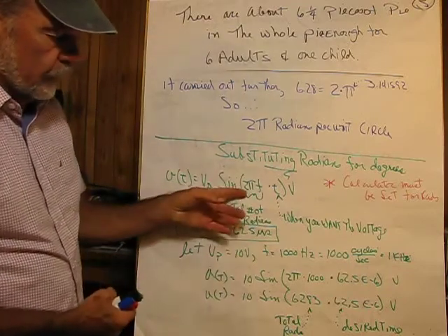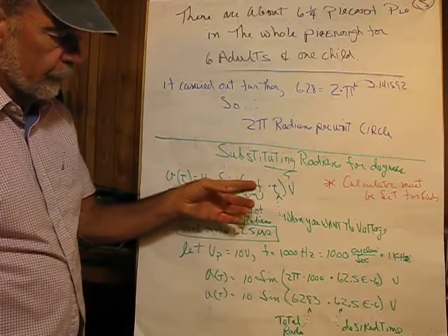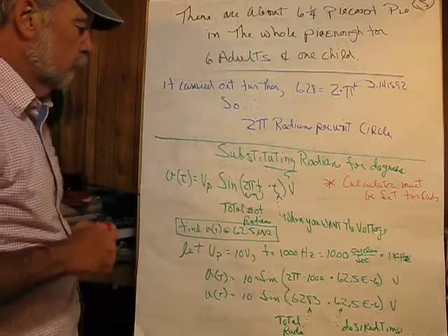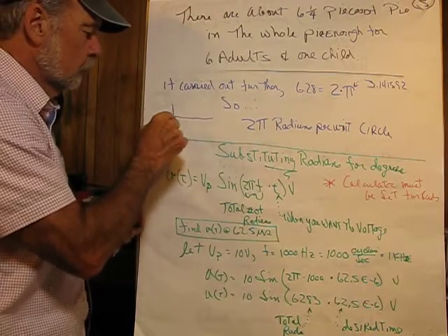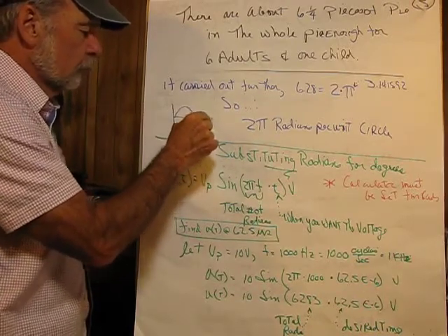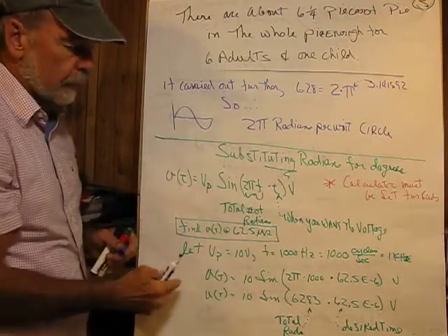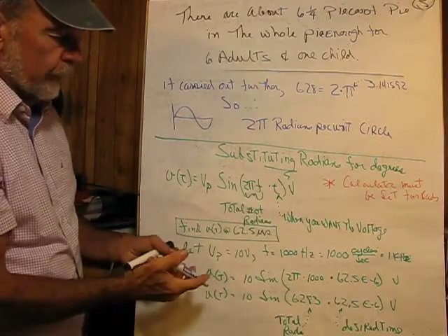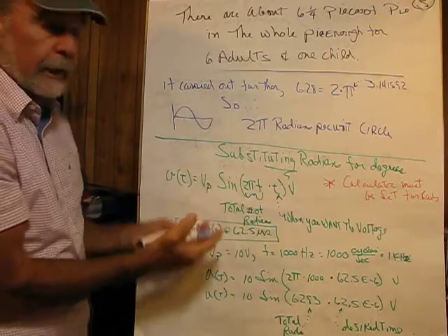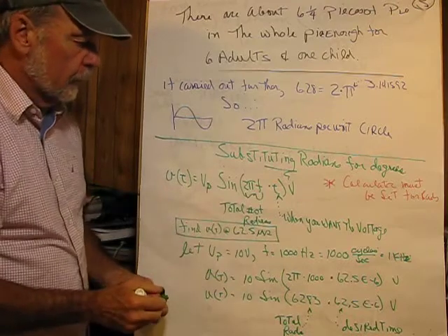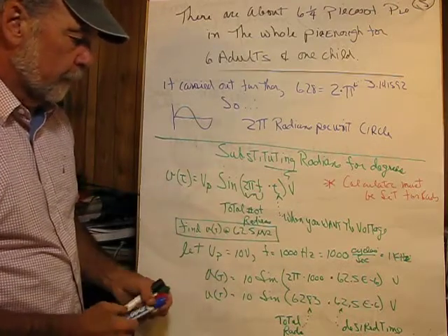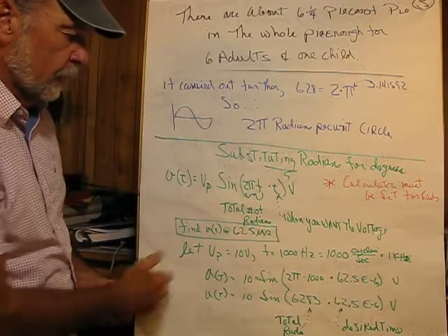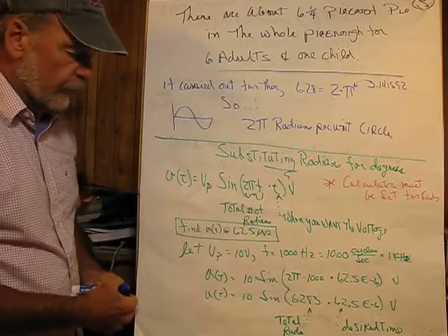And if we work out the units on this, we'd see that f is in cycles per second, that would be a cycle, how many cycles per second times the time, which is in seconds. So what we end up with is radians for an argument for the sine wave. So the argument has to be dimensionless, and the units will tell you whether that in fact is correct or not.